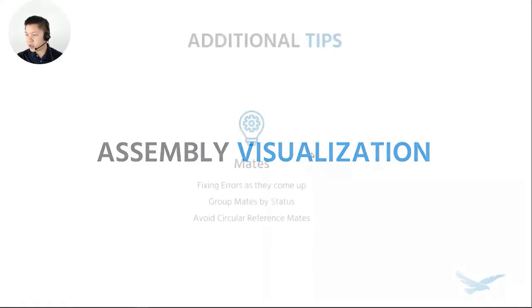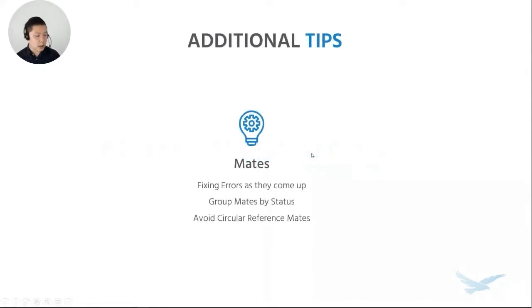And we'll take a look at some of the additional overall tips. Again, just making sure that we take care of this now so that later on it doesn't bite us, is fixing errors as they come up. Ideally, we'd like to model and have it set so that at the end, we take care of anything that comes up. But it's easy to fix them as they come up so that they don't compound. Because sometimes you'll probably notice in a part or an assembly, as you solve one thing, it cascades, right? Fixes another thing and goes from there.